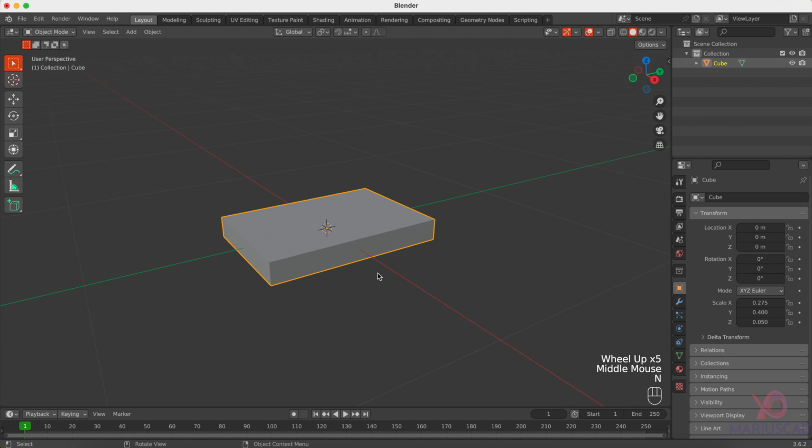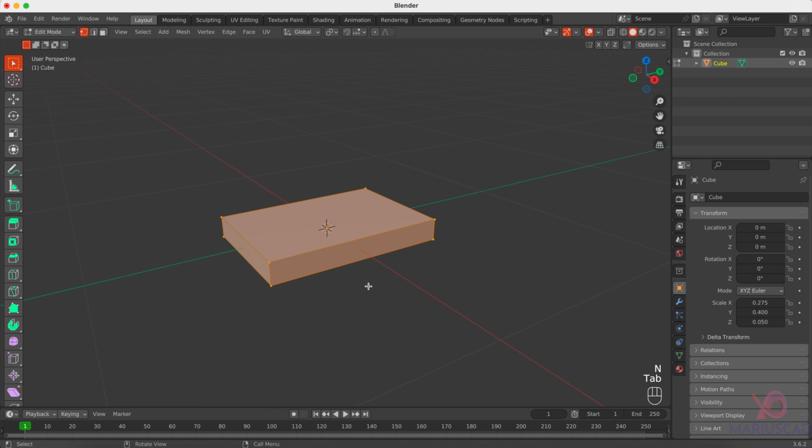After that, I will add some loop cuts. So tab key to enter in the edit mode. Okay, I will add this panel and I will write here instead of 1, I will write 20 loop cuts. I'll do the same on the other side, so also 20 loop cuts, and on the lateral I will write just 10, should be enough.